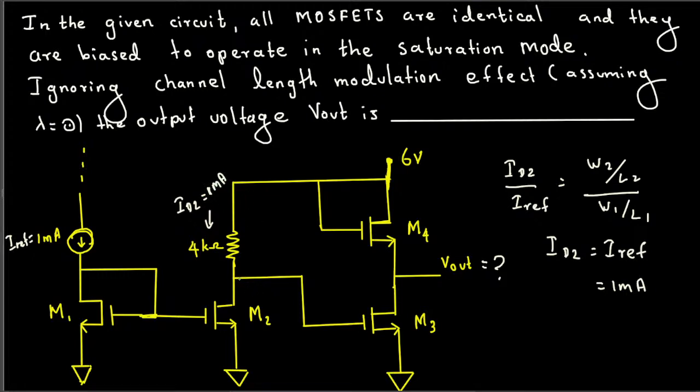And there won't be any current flowing through the gate. In MOSFET, there's no current flowing into the gate. So it means whatever the current goes here should be the exact current going here as well. So that's one more good thing you can know.